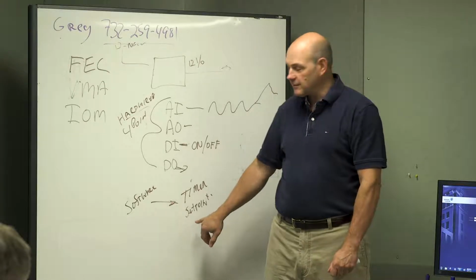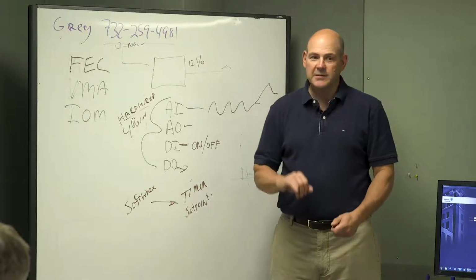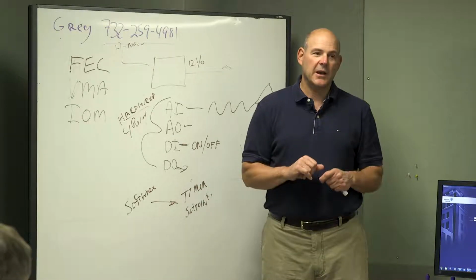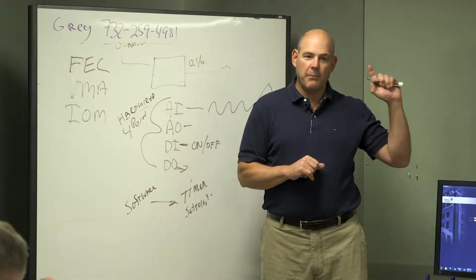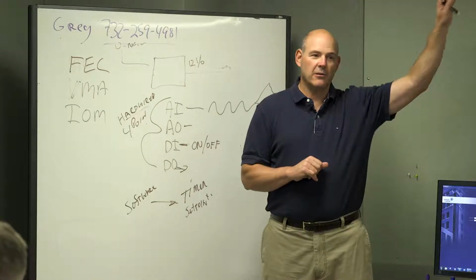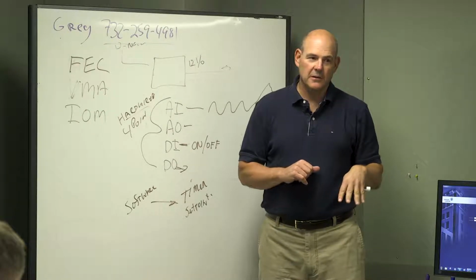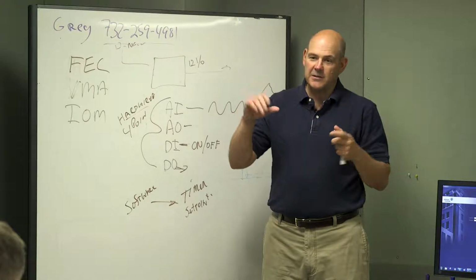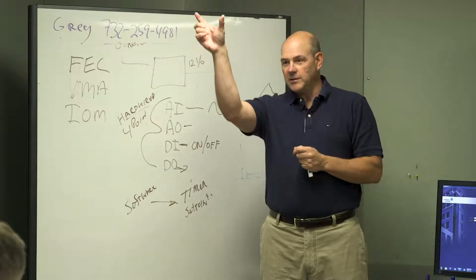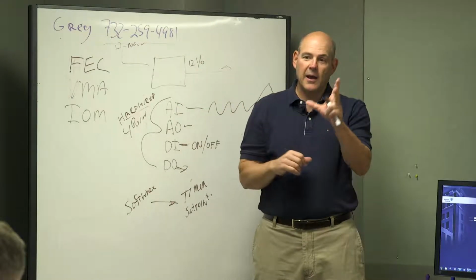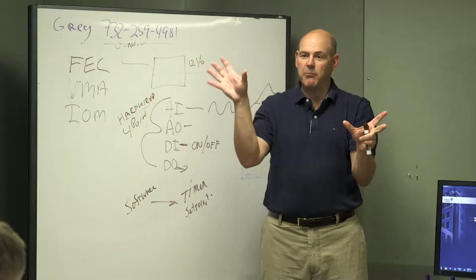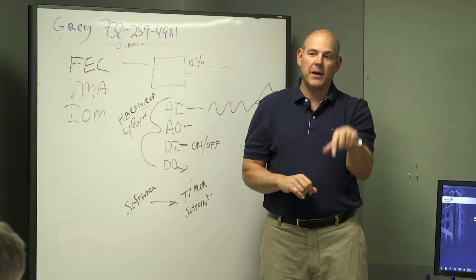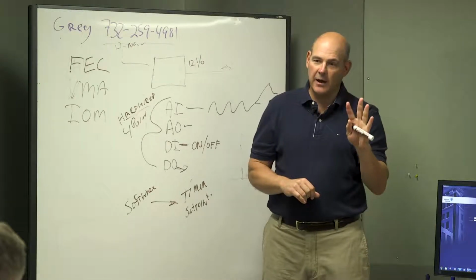You can't change it. And a timer is a time delay. So when we get status of a pump, we can now turn on the fans, turn on the chiller. So when you look on the graphics, you'll see there are set points on one side and commands on the other. So set points are software, commands are all hardwired. You're going to turn items on and off.